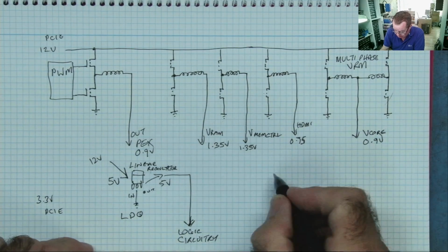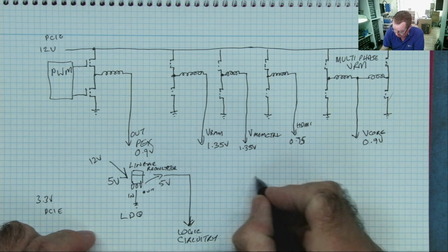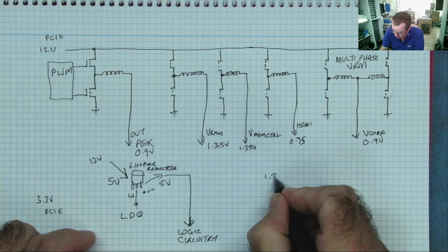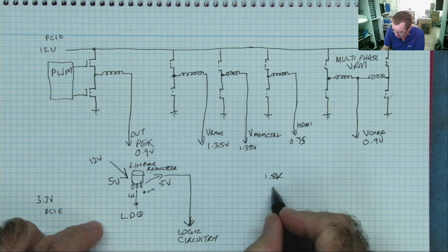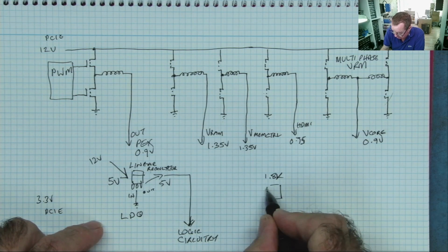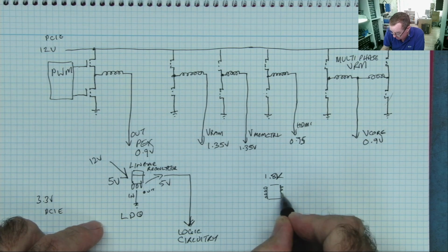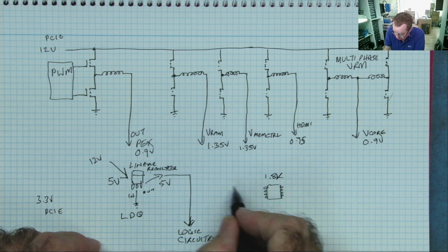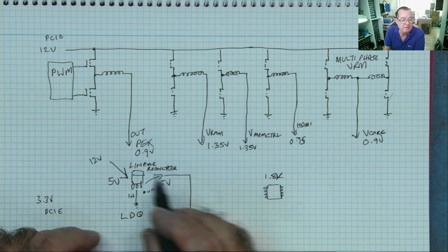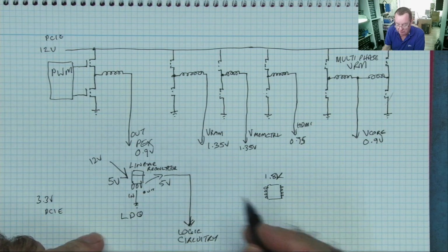And the one other voltage we have is the 1.8 volts. Now, the 1.8 volts usually uses one of these again. Quite often it's a little 8-pin chip, but again, don't worry guys, we will look at them. We'll try and find them when we measure some voltages. And this normally has either the 5 volt or the 3.3 volt coming in.